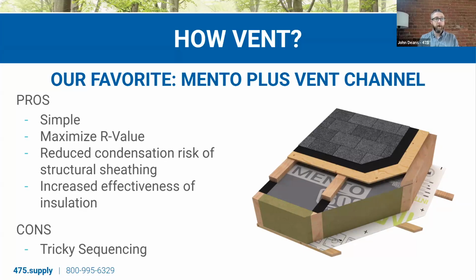So we're putting a vent channel above it before we put our structural sheathing on there. Again, that channel ideally is 2 inches and above. And what we're seeing in this diagram is you've basically got your Mento Plus, and then that black strip is a double-sided tape, Tescon Nidec, that allows you to seal the fastener penetrations that are going to go through the battens that create the vent channel, and then the sheathing, and then the underlayment and the roof on top of it.